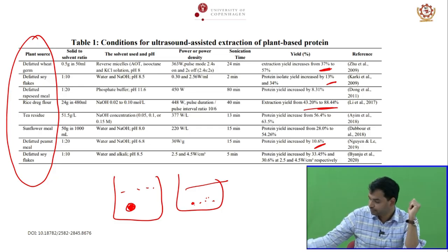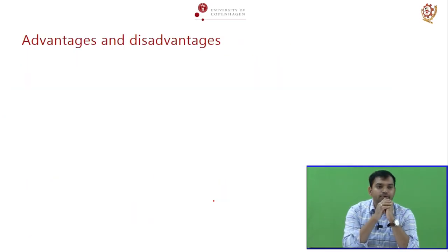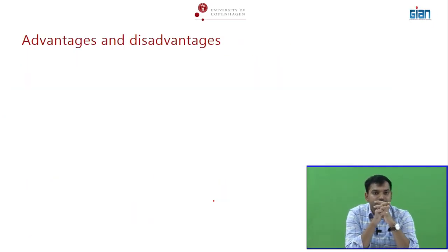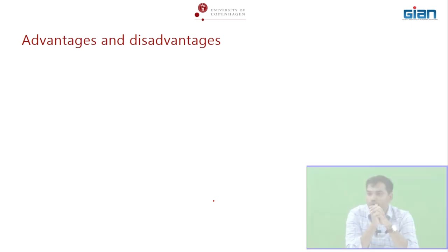Okay. All right, so can you mention one or two advantages and disadvantages of ultrasound? What is the advantage? The time is money, it's less time consuming, the process efficiency will be higher. I agree with you. Any other advantage? One other claim is that ultrasound is a non-thermal process. Yes, ultrasound is a non-thermal process provided you maintain the power and time properly.